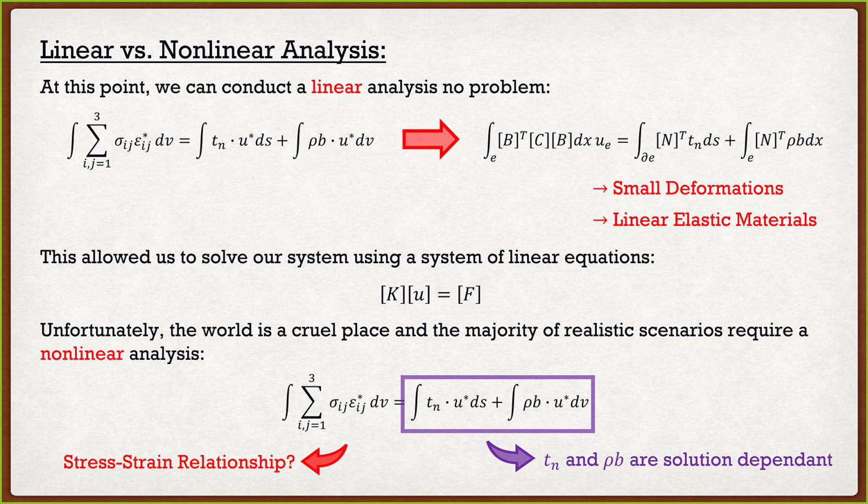One of the most low-key assumptions that we made in that small deformations was that when we're doing these integrals, remember, we're integrating over the element, but when we were doing those integrals, we were integrating over our undeformed or our reference domain. And again, if we're doing small deformations, that's perfectly valid. If I have a beam and all I do is tilt it just a little bit, well, the reference domain and the deformed domain are going to be very similar, so that integral is not going to be too bad.